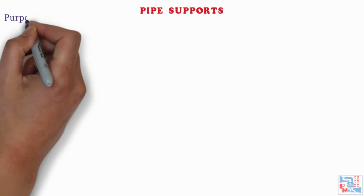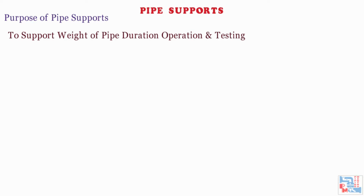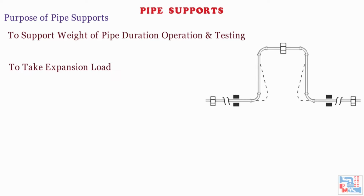At first, we will identify the purpose of pipe supports. Its main purpose is to support the weight of pipe during operation and testing. Next is to take expansion load. Whenever thermal expansion is restricted by support, it introduces additional load on the support. Support must be designed to take this load in addition to all other loads.